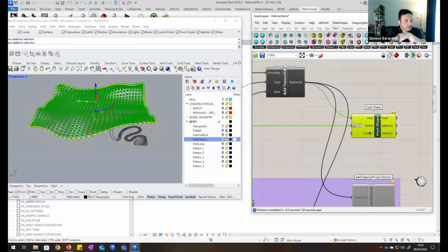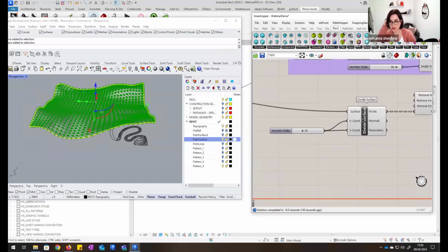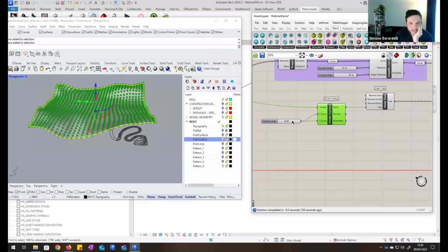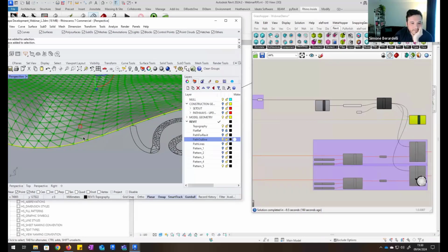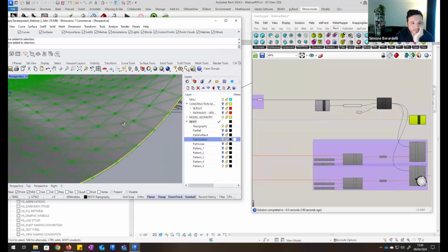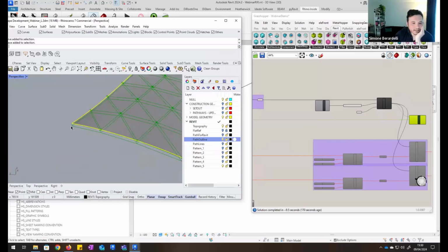And I can also feed the creases. Essentially, you can control the amount of points that you will transition into Revit. If I understand correctly, the more points you have, the more accuracy and smoothness you will have on the resulting surface within Revit. Exactly. I can decide the definition in here. And with this shape node, when I click in here, I have a preview of what is happening in Revit. You can see the top of the toposolid is there, and all of the meshes are triangulated across all of those points.